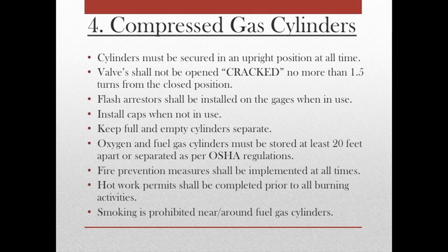Compressed gas cylinders. The following rules apply when working with compressed gas cylinders. Cylinders must be secured in an upright position at all times. Valves shall not be opened or cracked more than 1.5 full turns from the closed position. Flash arresters shall be installed on all gauges when in use. Install caps when not in use. Keep full and empty cylinders separate. Oxygen and fuel gas cylinders must be stored at least 20 feet apart or separated as per OSHA regulations.